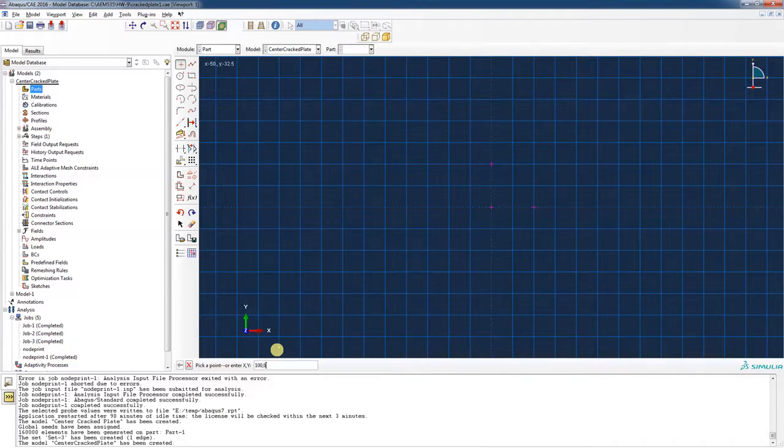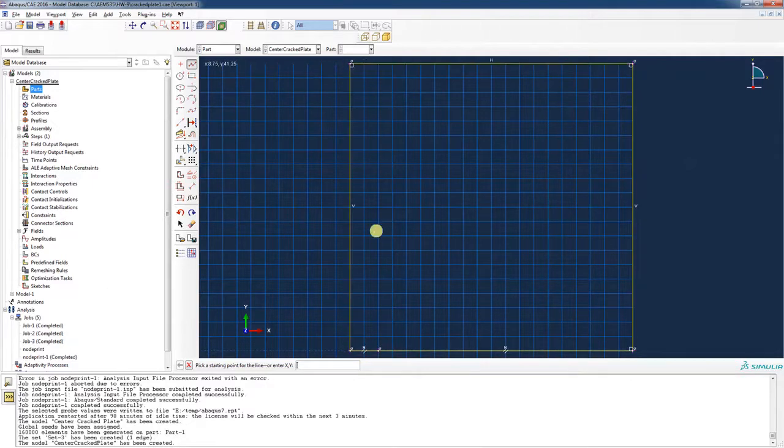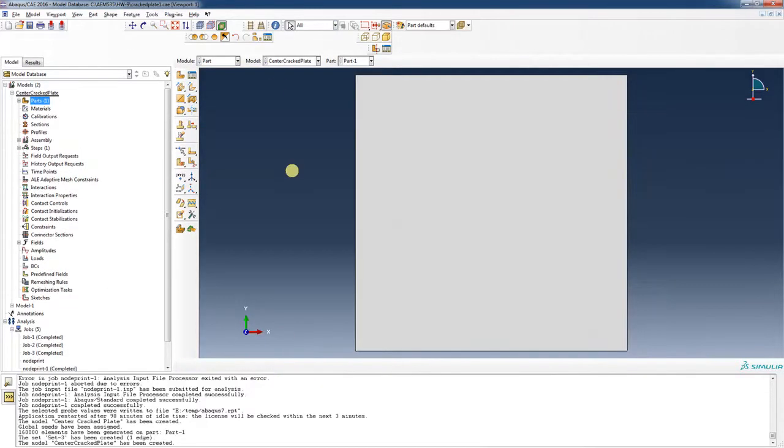100, 0, 100, 100, 0, 100, and I'm going to get rid of this point right here, so I put that in extra. So let's resize this. Now we can see the outline of what we have going on here. We're going to use a connect the points option, and we're just going to go around this and hit all these points pretty quick. Since we've used ABAQUS quite a bit now, I'm going to go a little bit faster through some of this. Alright, we're done.